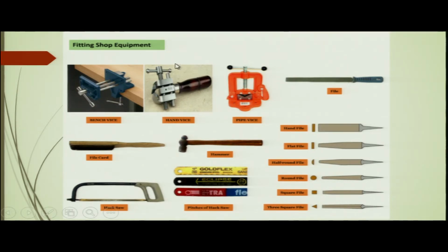Here you can see that this is a hand vise. So, this is handheld. The purpose is the same, that is to clamp a workpiece, or a part in between the jaws. So, here you can see the jaws are like this. So, you can rotate this handle. This is the lead screw in this case, this is the support, and these are the jaws. Okay. So, these jaws will be moving, and one will be the fixed jaw like in this case, and between the fixed jaw and the moving jaws, the part will be clamped.